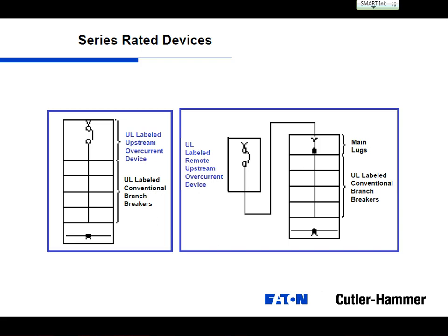In this case, both of these panel boards may have the same breaker upstream in the main distribution switchboard at your service entrance, and you're feeding all the way down to either a panel board with an identical breaker, or you can put main lugs only there.